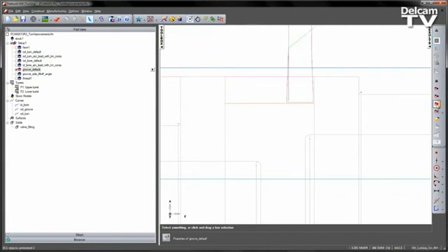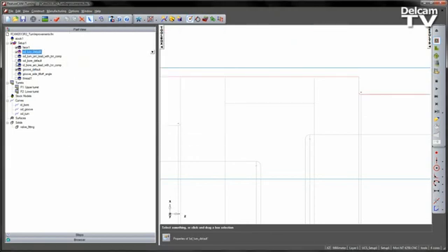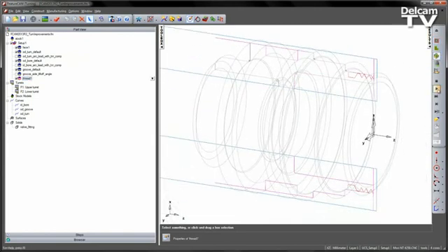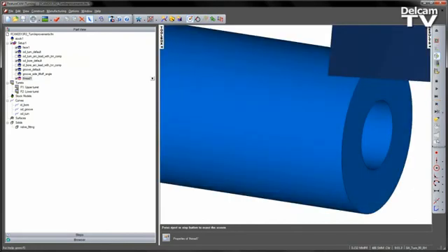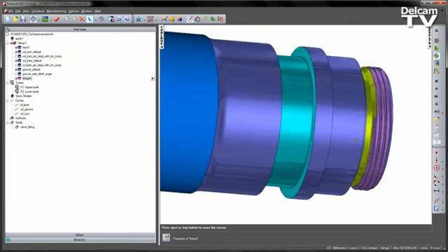Again, we get the first plunge. We're not going to move sideways in this first plunge because we've only just cleared the material. But now when we get to the second plunge, as we retract out, we use that lift-off angle to clear the part. This continues to repeat throughout the process. I'm going to turn on the rest of my features just to complete the part. Dropping my speed of simulation down to get my finished component.